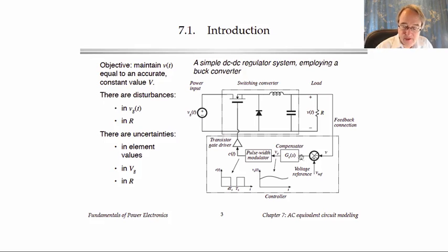The difference is called the error signal, and this signal coming out of the summing node is a measure of how much the output voltage differs from the desired value. That error signal is put through what's called a compensator circuit that typically is realized with an op-amp or similar circuitry to produce a control signal Vc that controls the duty cycle of the transistor.